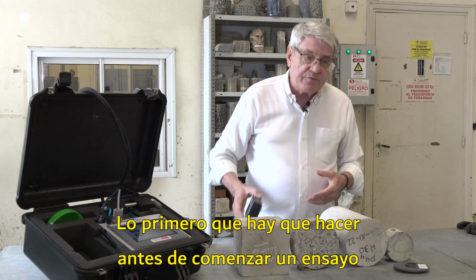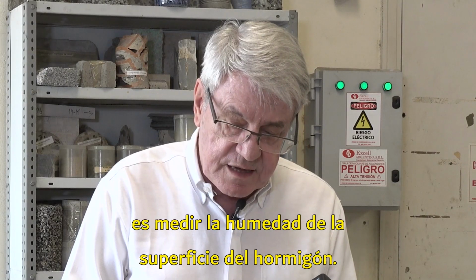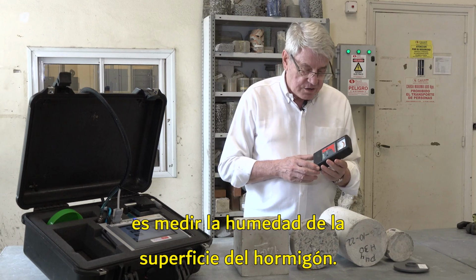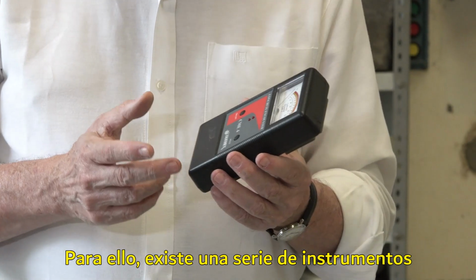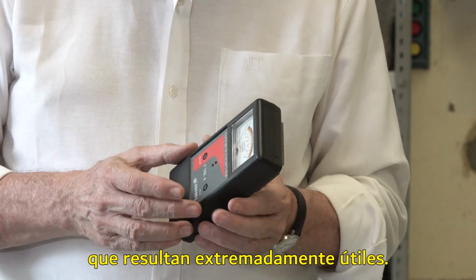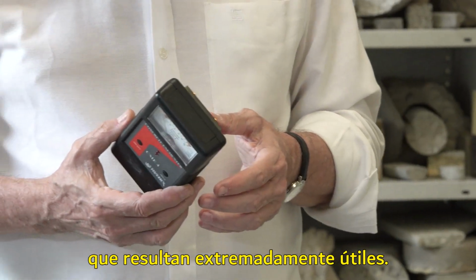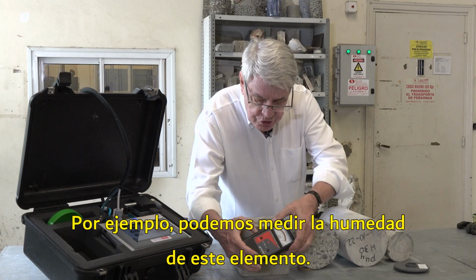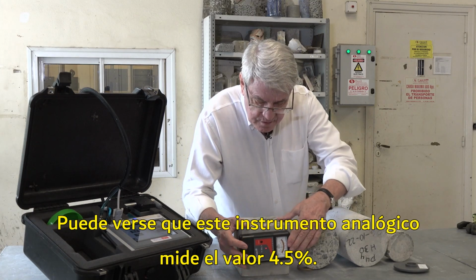The first thing we have to do before we start the test is to measure the moisture of the surface of the concrete, and for this there is a series of instruments of the Tramex family which we found extremely useful. For example, we can measure the moisture of this element. You can see the value.